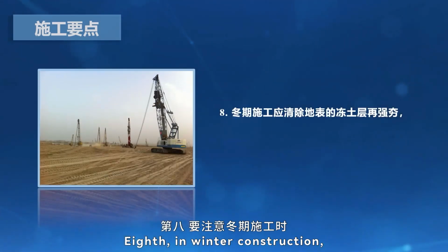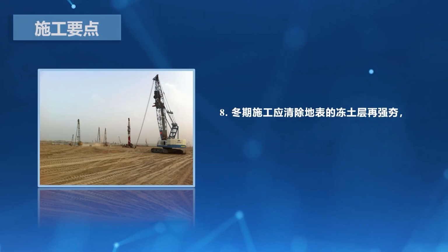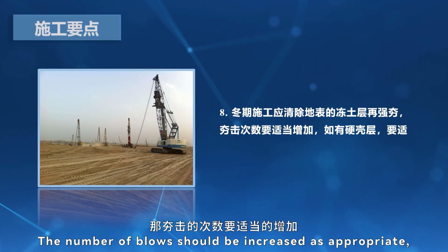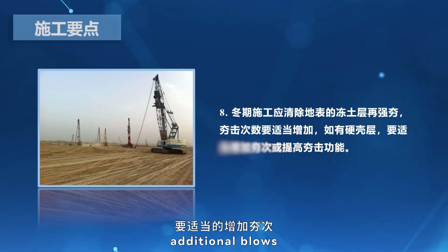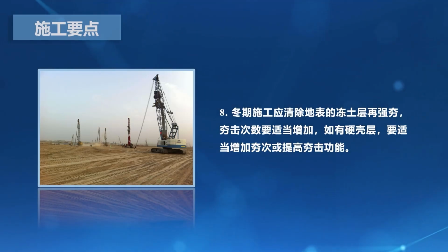8th, in winter construction, frozen soil on the surface must be removed before tamping. The number of blows should be increased as appropriate, and when there is a hard crust, additional blows or higher tamping energy should be applied.